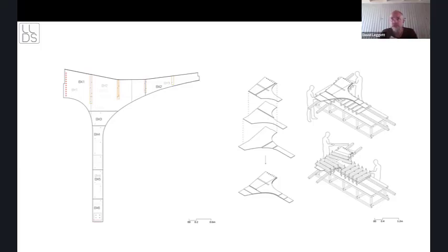And because anyone knows that polyurethane glue expands and foams up as it cures, it's so important to clamp the two layers together to stop that from happening. So we're running around, spreading glue, positioning the layer of the ply, and then quickly clamping it all down in place and running around tightening up bolts and things like that.